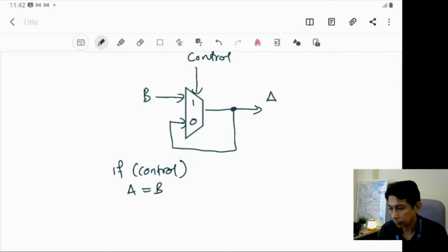Now, how to create a D latch. So this is how. All right, module D latch, D, clock, and Q. Input is D and clock, and of course Q you need to declare as output reg, because Q is the variable inside the always block.